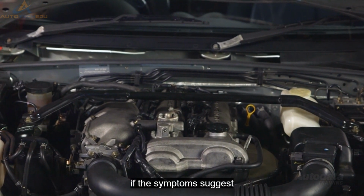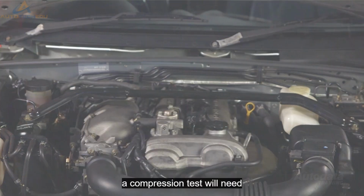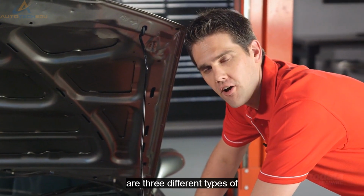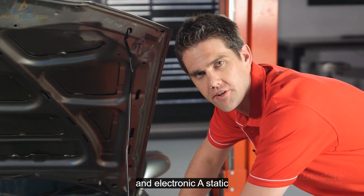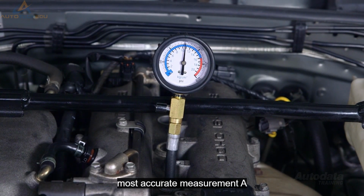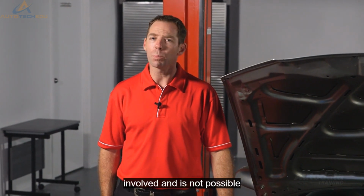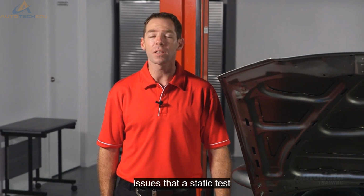If the symptoms suggest that the cause of the problem may be cylinder pressure loss, then a compression test will need to be performed. There are 3 different types of cylinder testing: static, dynamic, and electronic. A static compression test is relatively easy to perform, and when done correctly, will give you the most accurate measurement. A dynamic compression test is more involved and is not possible on all vehicles, but it can point to potential issues that a static test cannot.